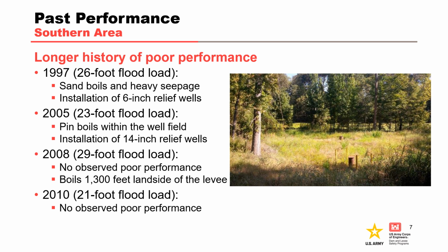In response, the Vicksburg District installed an additional three 14-inch diameter relief wells to further relieve foundation pressures. During the 2008 flood event, no performance problems were observed at the relief wells, but sand boils were observed approximately 1,300 feet land side of the levee at the shore of Eagle Lake. Finally, in 2010, with a flood load of 21 feet, no performance problems were observed near the well field or near Eagle Lake. So contrary to the northern area, which saw performance degradation with time, the relief wells in the southern area seem to have provided adequate seepage pressure reduction to prevent poor performance in the immediate vicinity.